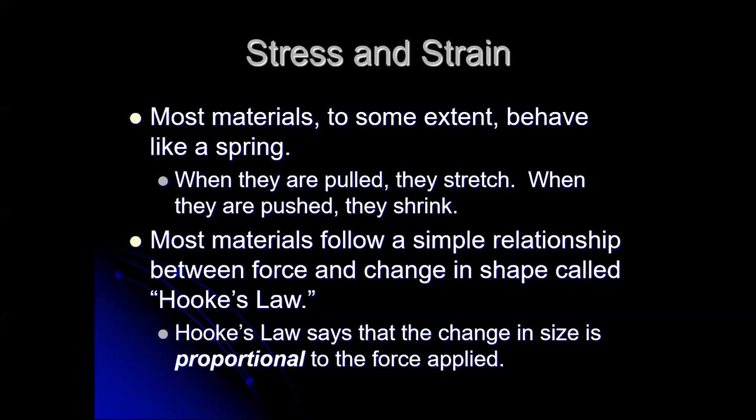So Hooke's law says that the change in size, how much deformation we get, is proportional to the force applied. So if we double the force, we get twice the extension or twice the compression. If we double the stress, we get twice the strain. If we quadruple the stress, we get 4 times the strain.